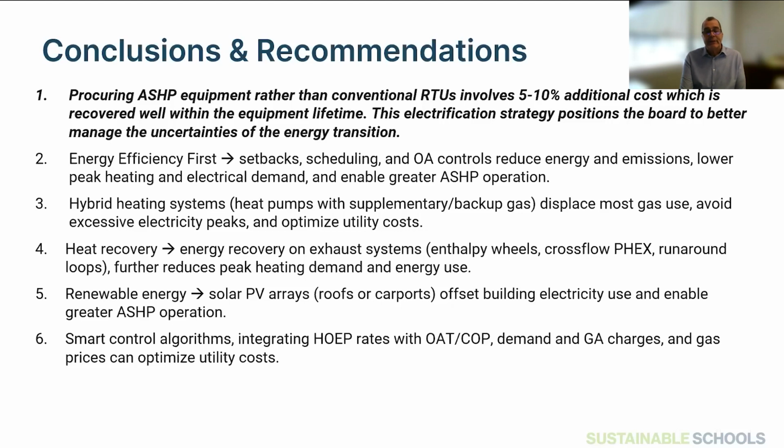So that step gets missed during the standard commissioning process. So we're finding we're having to go back and revisit that sometimes a couple of months or 6 months after the school has opened to ensure that what we think is happening is actually happening, because it's very difficult to tell on an automation graphic what is actually running.